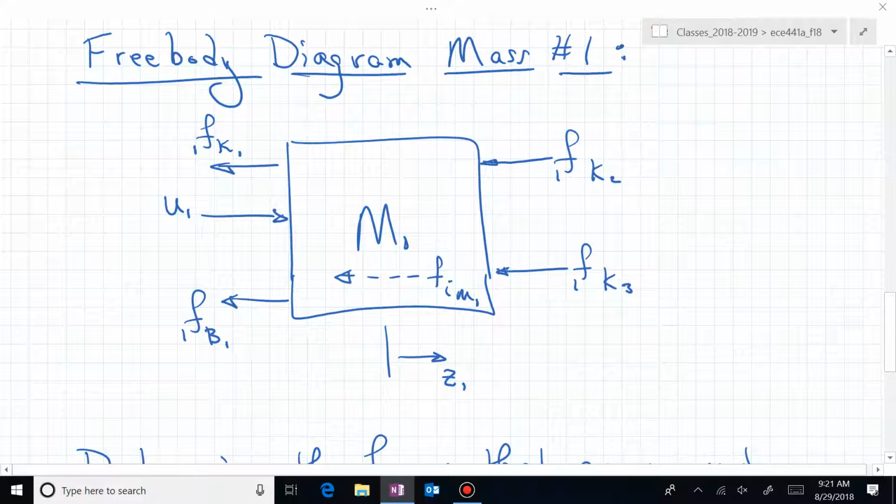I'm not going to weight that by some gamma, but you could if you had conversion factors that were necessary in your system. Here I'm saying that we have enough coefficients floating around, so let's not introduce another one. Is that okay? So U sub 1, you could put a scaling factor in front of it. Here I'm not going to. But if that was being produced electrically, you obviously would have a conversion factor to convert that voltage or current into a force, and so you would have a scaling factor associated with U sub 1.